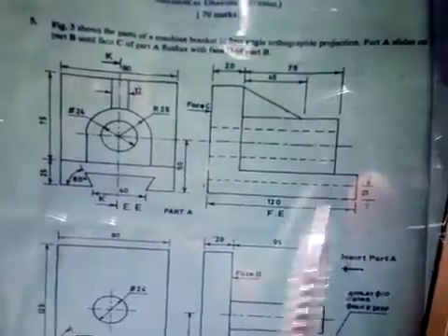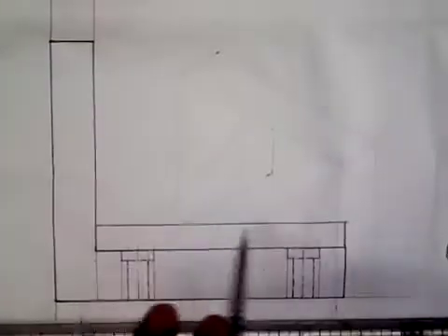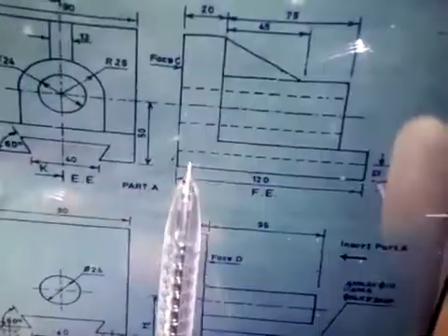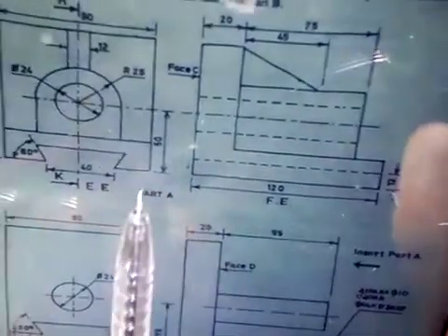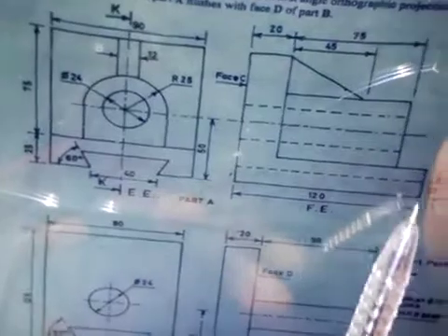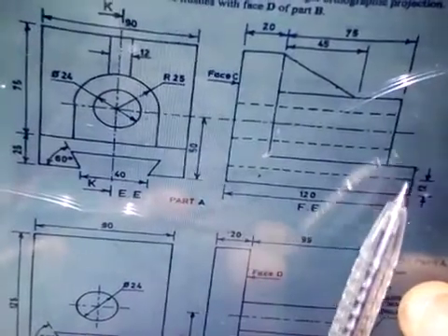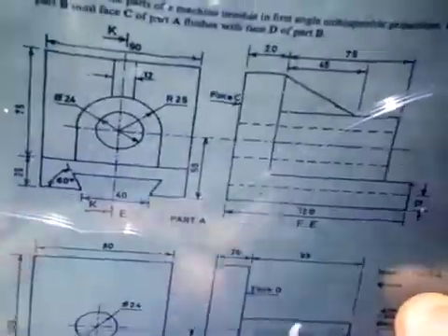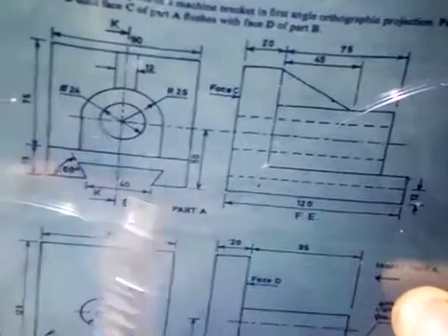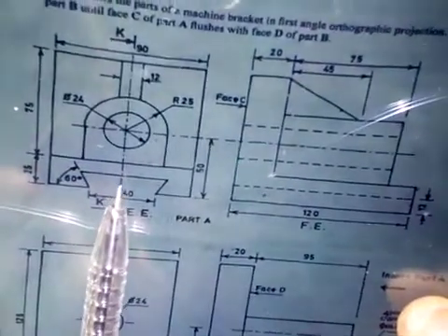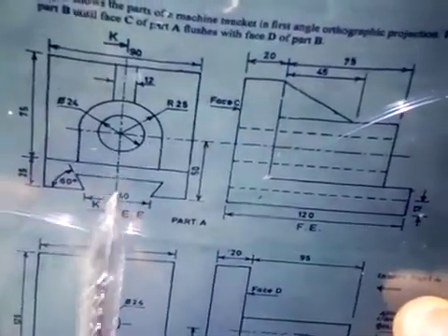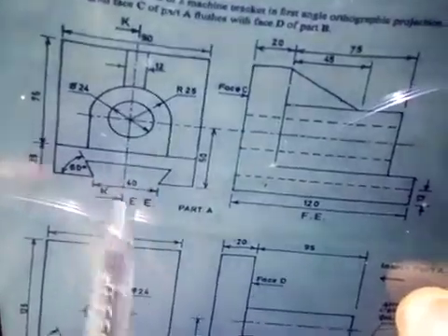So this line that I drew here is for this part. That is 12 millimeters. So then I'm going to take it because from here to here now is 25 millimeters. So if I remove 12 from 25, the rest will remain 13. That means distance from here to here is 13 millimeters. So I'm going to take that 13 millimeters up, which is for the distance from here to here. The cutting plane cut it and I'm going to hatch it.